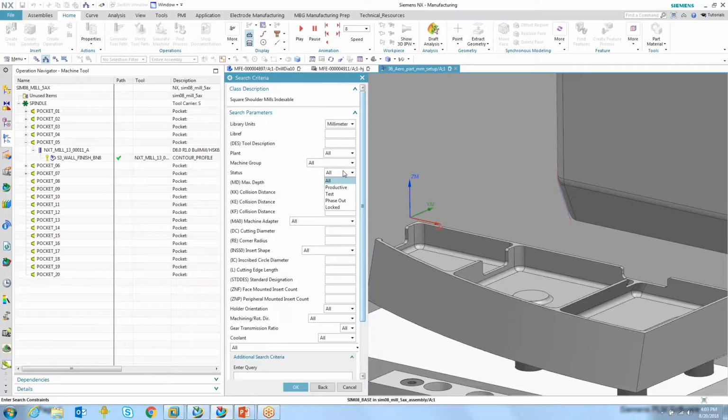Maybe it's something that you guys didn't like how that cutter worked. It was a different coating or something like that that wasn't working well. You're getting a lot of galling on the tool, so you phase that out, and that's important because of this status. If you come back to use that same program or that same tool the following year, you can see that tooling assembly has been phased out, and it's something you should look into and maybe reprogram with something else.